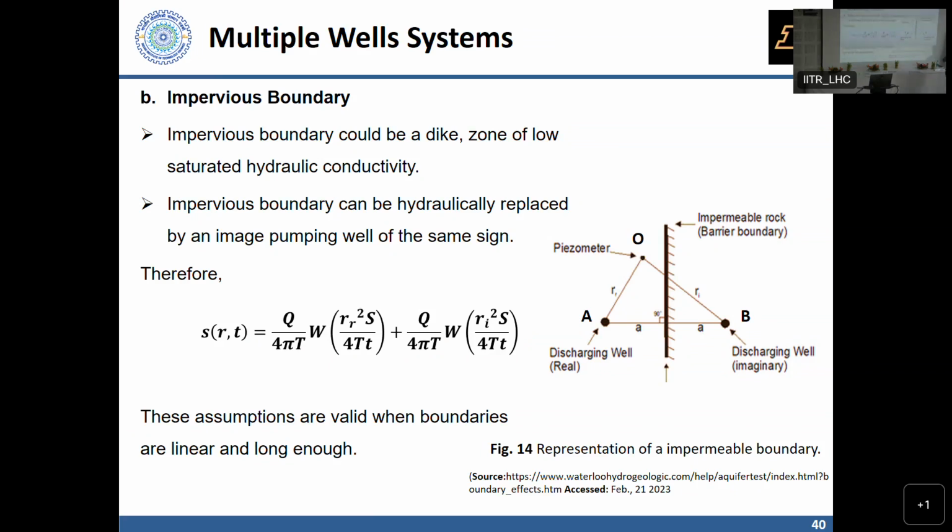So what do we require for no flux? The water is going to move because of a change in the total head, so dH/dr has to be non-zero. If I superimpose these two curves, the combined drawdown curve is going to be like this, because these two slopes are going to be exactly in opposite directions. At this point this has zero slope, and therefore dH/dr becomes zero, which gives you mathematically why you get no flow.